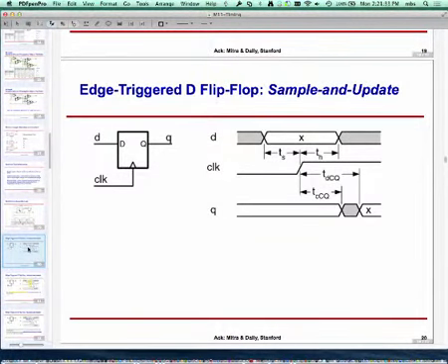What that translates into is a little bit deeper into how these flip-flops work. What's happening in the flip-flop is it's waiting for a clock edge to come. When the clock edge comes, it takes the data at the input and stores it in memory, and also puts it on the output. Now, if the data value were changing at the same time as the clock edge is coming, the flip-flop will have a hard time figuring out what to do, because just as the clock edge is coming, the data is changing also. And if it's a register, then I may have multiple data bits. So all flip-flops